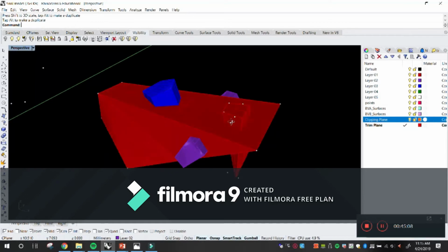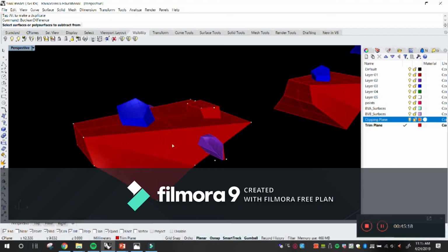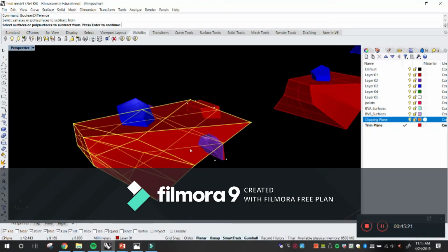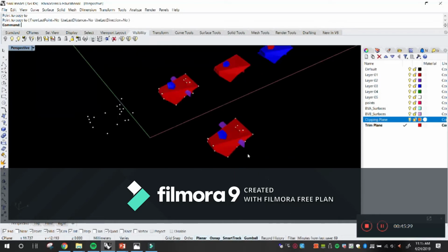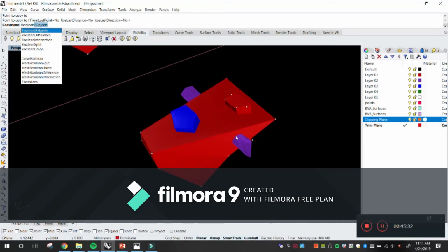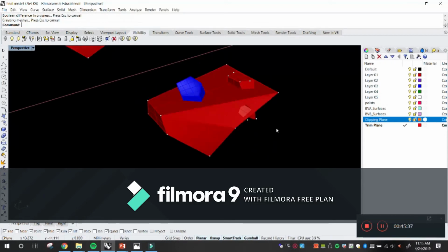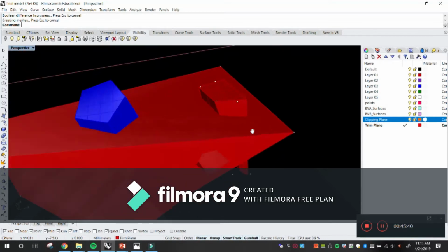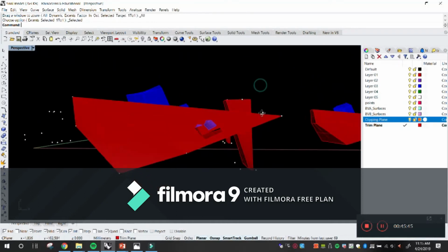And then I want to make a hole right there. Let's see if this is going to work. Now we also have Boolean difference. Surfaces to subtract from would be the red. And while you guys take notes, I'm going to copy this so that I don't lose those forms. I'm going to make a copy right here to the side. We'll play with this one. So again, Boolean difference. Select the object to subtract from, the object to subtract with. And then what does that do? It creates a hole. Recenter this, and we have that right there.